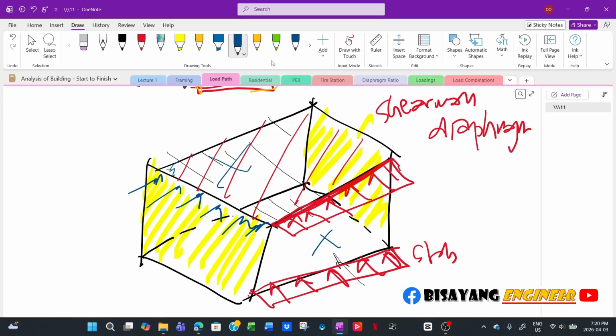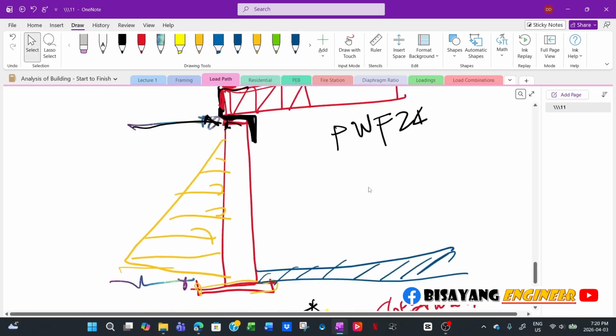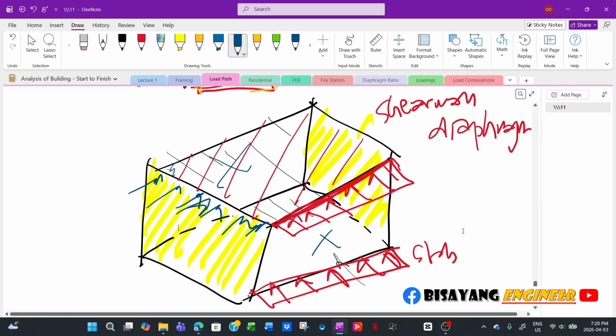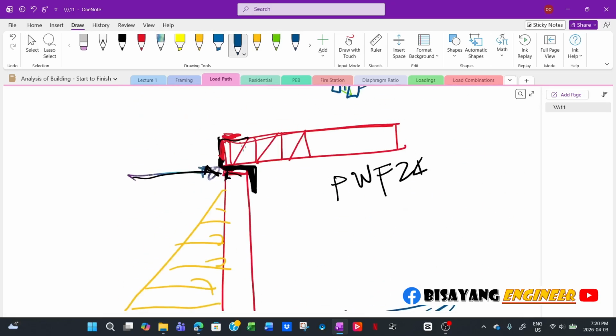So from the roof, you have gravity loads down to the foundation, but your foundation walls have lateral pressure, which is going back to the floor assembly, and then from the floor assembly down to the walls. Now in this direction, you have a lateral load perpendicular to the view, perpendicular to the paper here. So in this direction, perpendicular to this